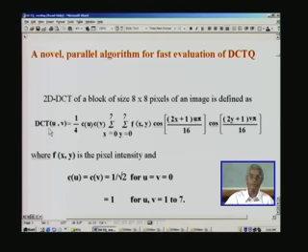In fact each of the coefficients is a conglomeration of all the pixels' information. For example, the very first coefficient is known as the DC coefficient, and that is obtained by assigning u, v equal to 0. So this will boil down to cos 0, which will be 1 here, and what is left here is only this. So this is nothing other than taking all the pixel intensities for the entire block, that means 64 pixels, and adding them together. That is what is implied here by this.